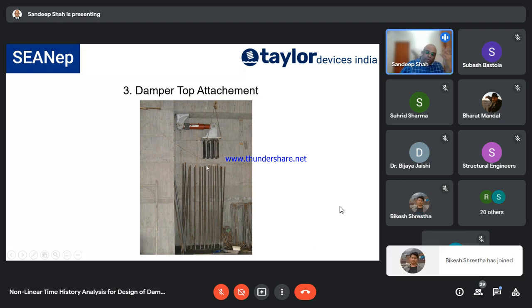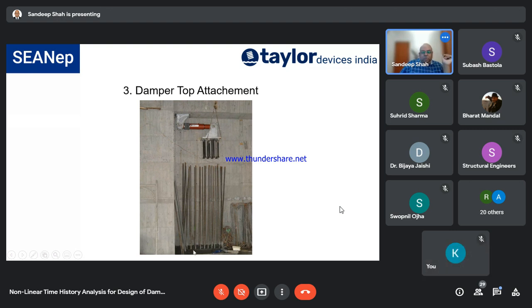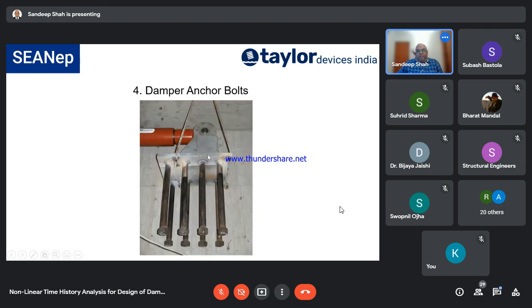I've shown you examples of flexible locations. Now I'm showing you an example of a very stiff location. So you anchor the vertical reinforcement, and you also put the horizontal. So don't feel there's no horizontal reinforcement. Over here, just because it's not showing, you put the vertical and the horizontal reinforcement, and the reinforcement will go all the way up to the base plate level over here. These are the anchor bolts which will get embedded.